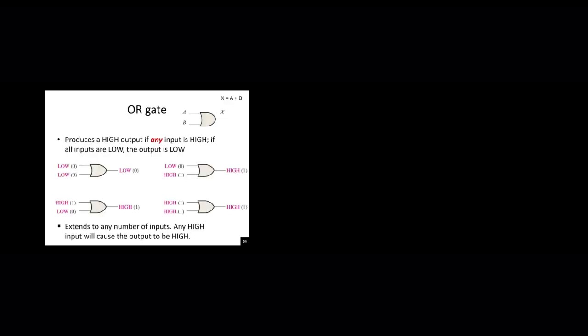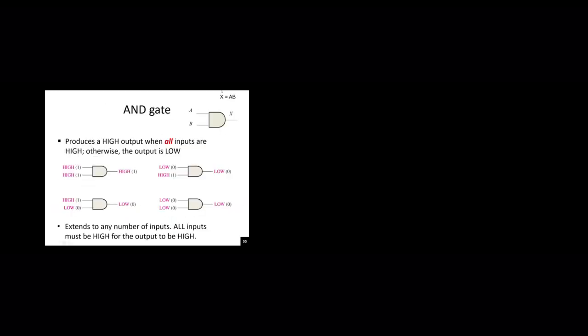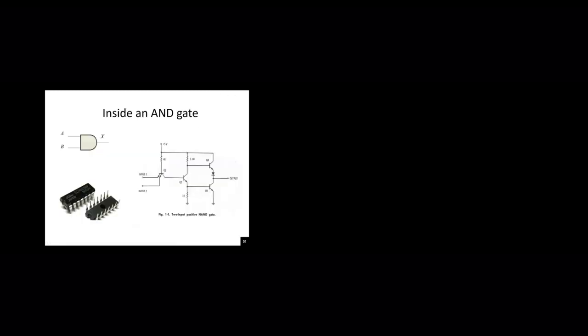And of course, you can buy an XOR gate as well. Oh, I should have said, apologies. So this symbol here is how we'll represent the AND gate when we're drawing out digital circuits. This flat line with a curve will always, in a circuit diagram, correspond to an AND gate. This triangle with a circle at the end in a circuit diagram will always correspond to a NOT gate.